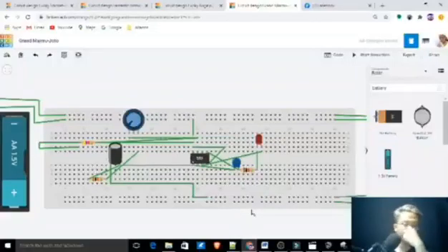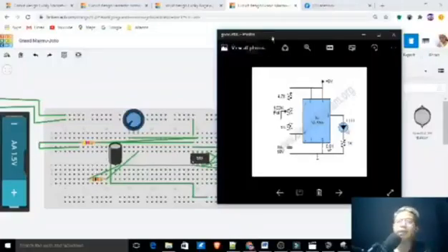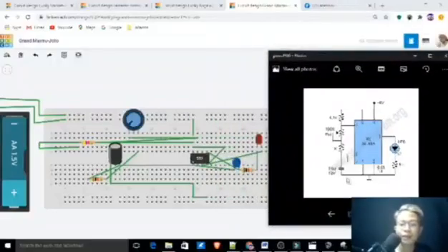So we need to check if we don't have a problem. If you see a problem, you have to change it. Okay, so let's get started. So from here, pin 3 is connected to our positive LED, from LED to the resistor. From resistor, we go to the capacitor. So the capacitor connects to pin 5 of the IC, and here we are connecting to the ground: capacitor ground, IC ground.